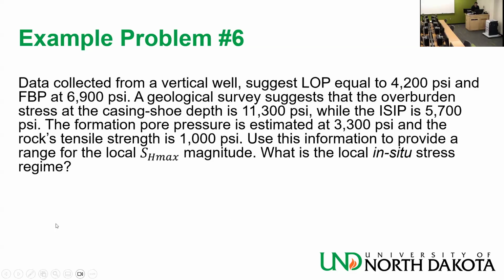But anyway, we have a lot of numbers and two questions to answer. But one question has two answers. We need to provide a range, constrain the range of the local SH max magnitude. So we need to find an upper bound and a lower bound. And then based on those values, understand what kind of in situ stress regime we have: normal, reverse, strike-slip, etc.